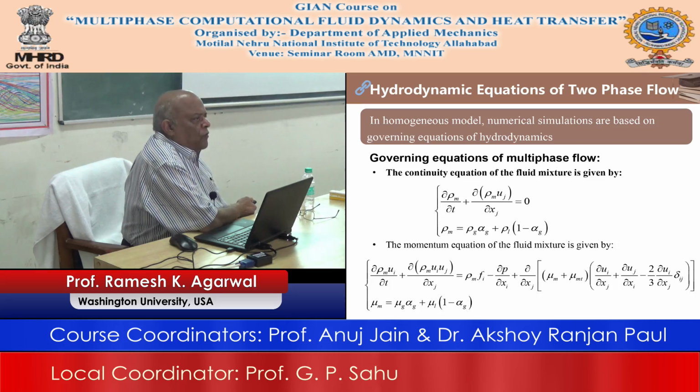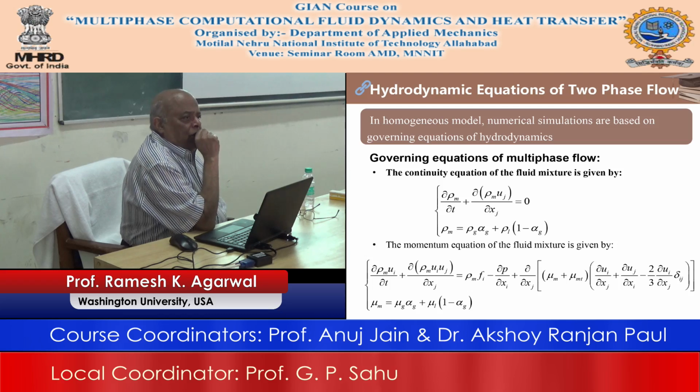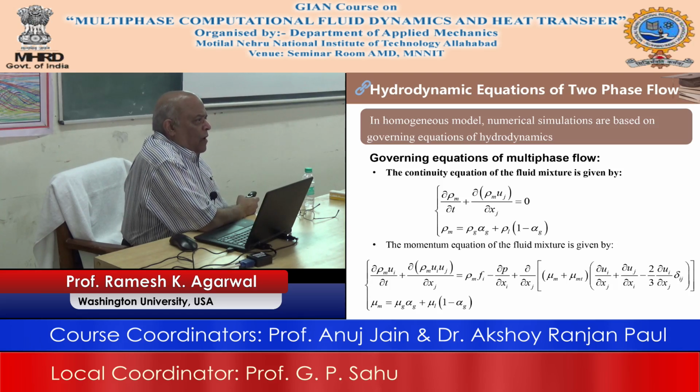So if you have to account for the effect of turbulence, you should, because turbulence does affect the behavior of the air bubbles, and that means turbulence does affect the region of air versus the region of water. So turbulence plays a very important role, and the flow is always turbulent. Although even if the Reynolds number is lower, maybe, more normally it is a couple of thousand or more based on the diameter.